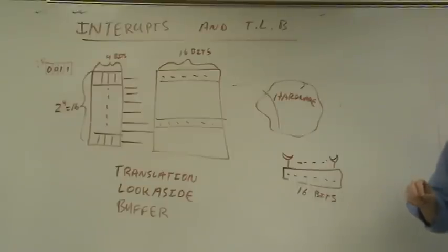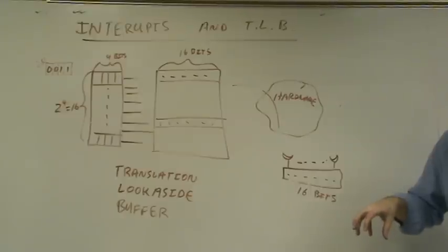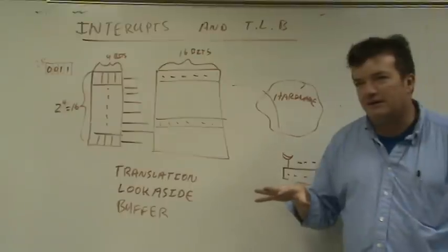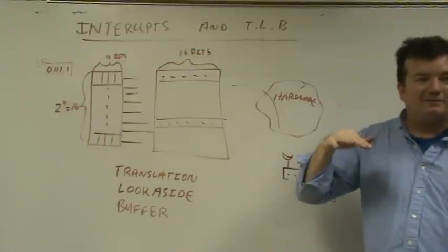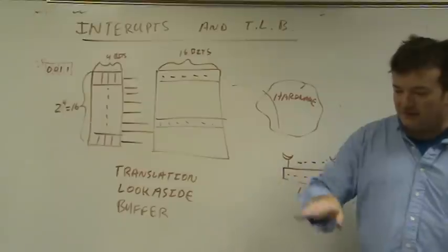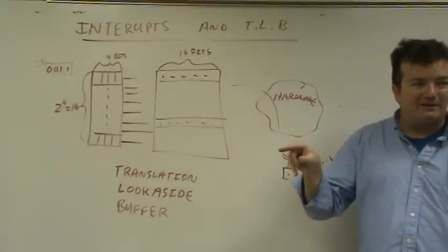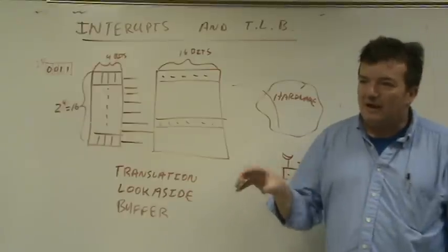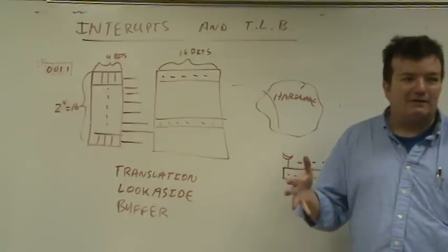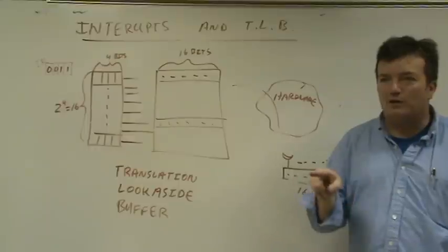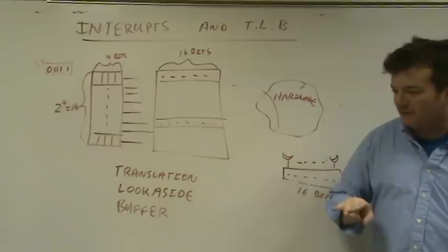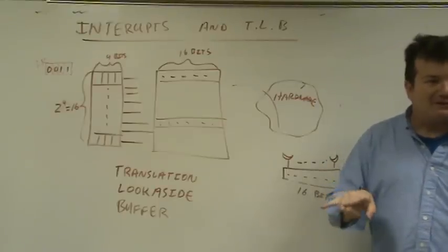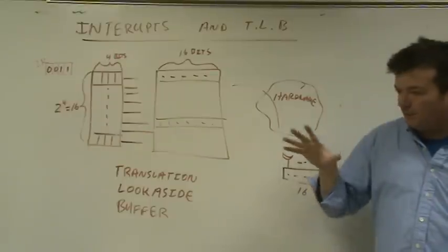So for example, if you're moving your mouse around on a computer, we could have software that says, if the mouse is currently over this link, then, like sometimes when you put your mouse over a link at the bottom of the screen, it lights up what would happen if you click it, but you haven't clicked it yet. So as you're moving the mouse around, actually events are happening. We could have software that's constantly tracking where you are, but that could take a lot of time. It might be better to just have a hardware register that throws numbers in, and then based on what number gets put in, determines what event is happening.